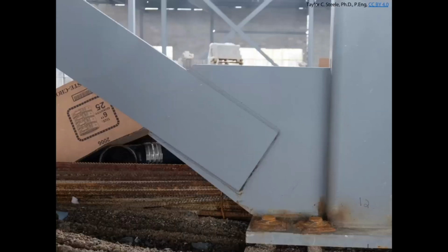And we're going to, at some point today, talk about this example where we had the welded tension member at the other end in that example building on the north side here. And basically, we looked at this example the other day, at the end of lecture on Friday, we calculated the resistance of these fillet welds in shear. And so today we're going to look at the effects of those fillet welds and their position on the tension members and how they might fail in the net section.